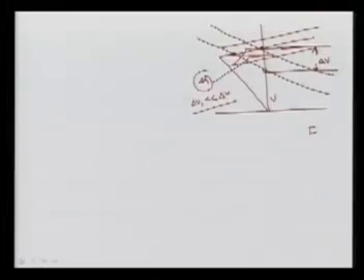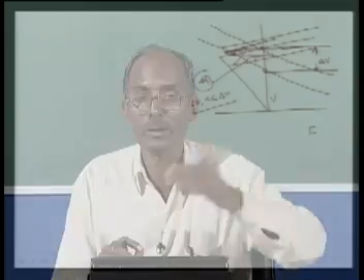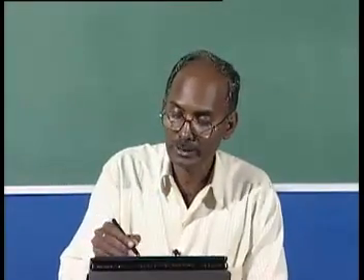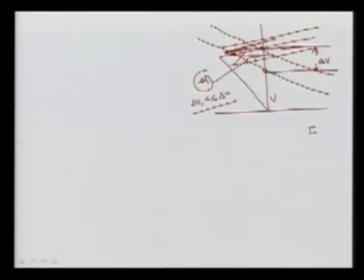At the same time, we can shift these characteristics here and there by changing the firing angle, and even with this load line we can maintain the voltage and get this characteristic. The voltage can also be fixed at the terminal voltage. So whenever load and voltage variation takes place, by changing the firing angle we can change the characteristic and maintain the terminal voltage at its rated value.